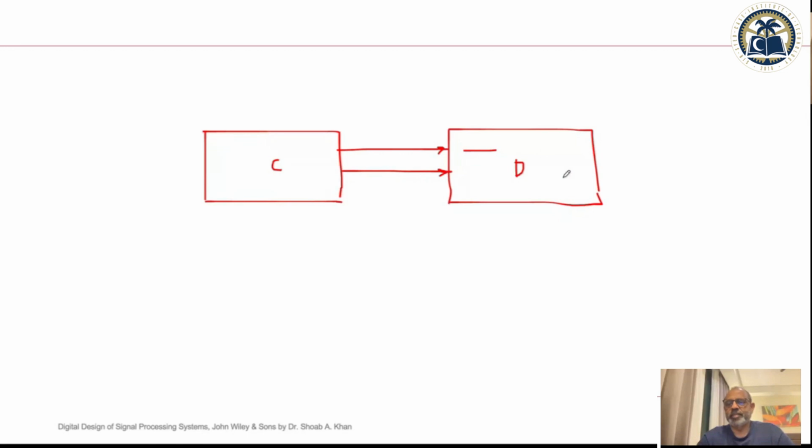Okay, I want the data path to have the memory. Obviously, I want the data path to have the memory, which is the FIFO. I want the data path to have all the three registers: read pointer, write pointer, and the count register. Okay. And I want just two signals from the controller, two signals it is sending. One is write enable, yes, you can write. And read enable, yes, you can read.